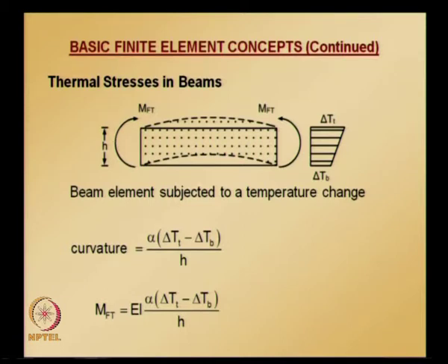So using that approach, the equivalent load vector turns out to be this. Because there is no shear along the span of the beam, only bending moment will be there, and putting the fixed end solution in a vector form and reversing the sign, we get the equivalent load vector.